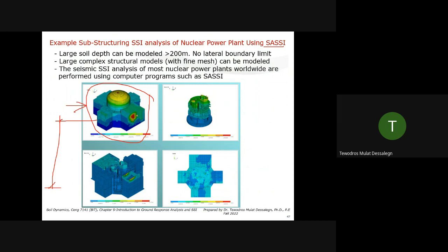In my time, it used to take at least a month sometimes to solve it for those 60, 70 frequencies. And we solve it for different soils. The soil itself is not one constant. We use average soil property, upper bound and lower bound, at least 3 soil parameters. So the simulation is too much. It takes months to get the whole response at the end.